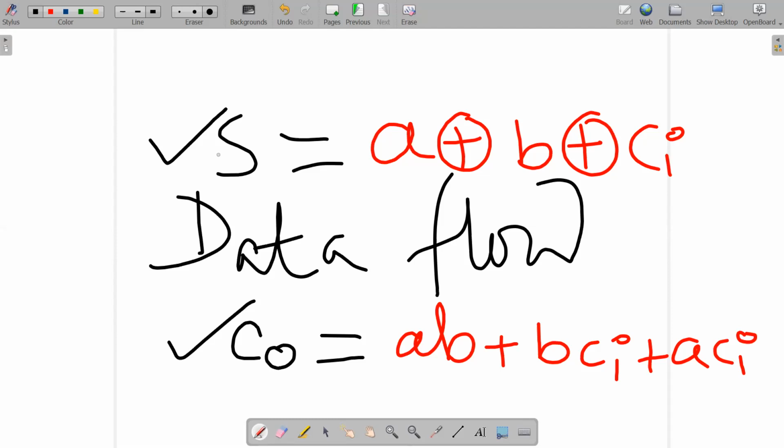Suppose you are going to design a 4-bit full adder. To construct a 4-bit full adder, you need four single bit adders. You know that thing. Suppose you want to add two 4-bit numbers. For that you need four single bit adders. You have already designed the single bit adder, so no need to write the code for the single bit adder again.